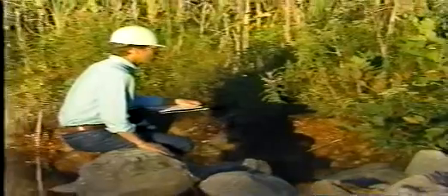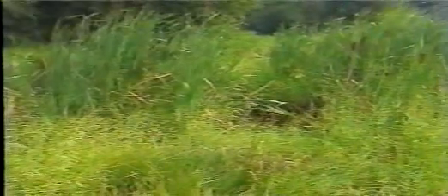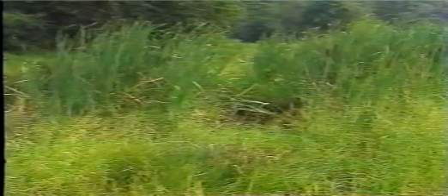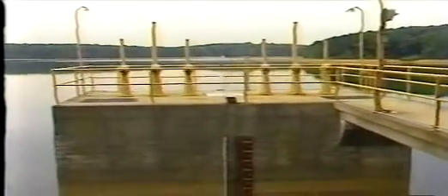During this process, known as piping, embankment or foundation material is carried away at the seepage exit point, forming a pipe. The pipe can enlarge and lengthen rapidly and lead to failure of the dam. Watch for seepage that appears for the first time, increases suddenly, or is cloudy. Areas of lush or water-loving vegetation can also be signs of seepage. Seepage is influenced by the level of the reservoir, so make a note of the reservoir level at the time of your observation.